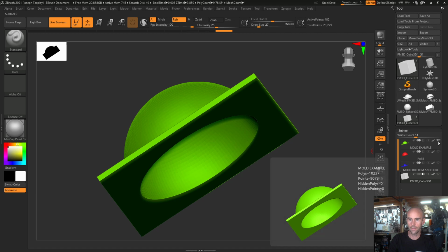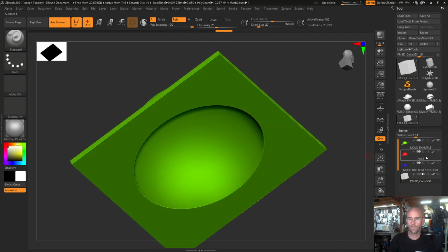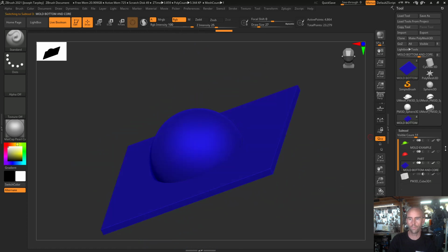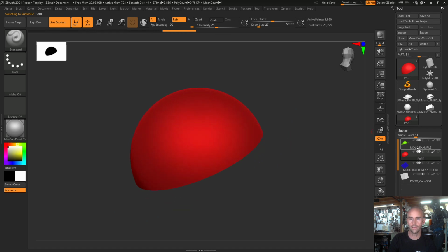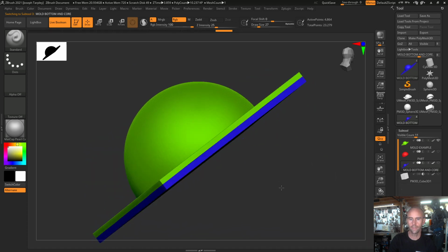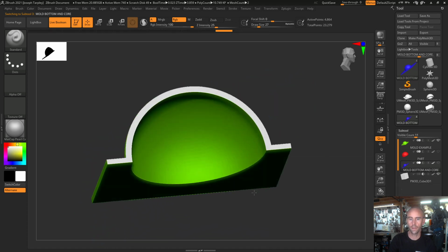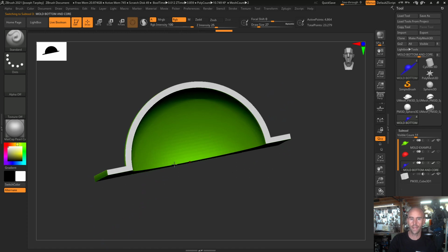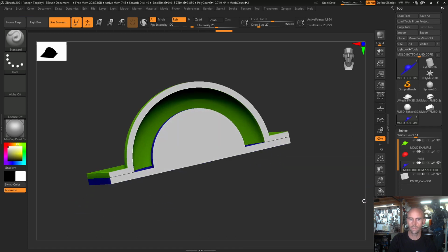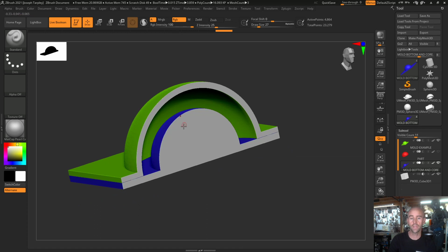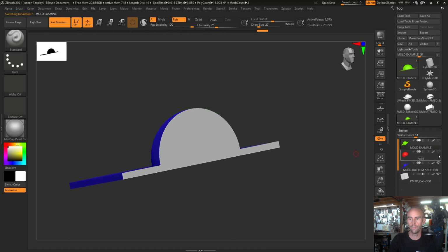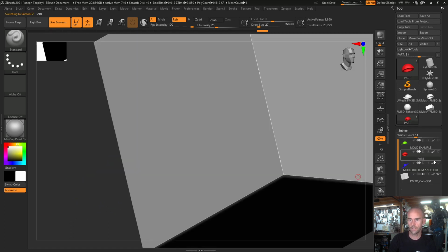I'm going to turn this off, and then we've got the mold. Let's say this is the top of the mold, and then we've got the bottom of the mold with the core. So this little guy would punch out this hole on the inside, and then this would be the top. These would close like that, and you'd have your pieces here. I can turn this on. Now there should be a little part line here so you can see the halves, but oh, I see what I did. There we go. So this would be kind of the inside of the mold, and that cavity is where the part would be formed, which would be our little red piece here. So anyway, let's get to it.